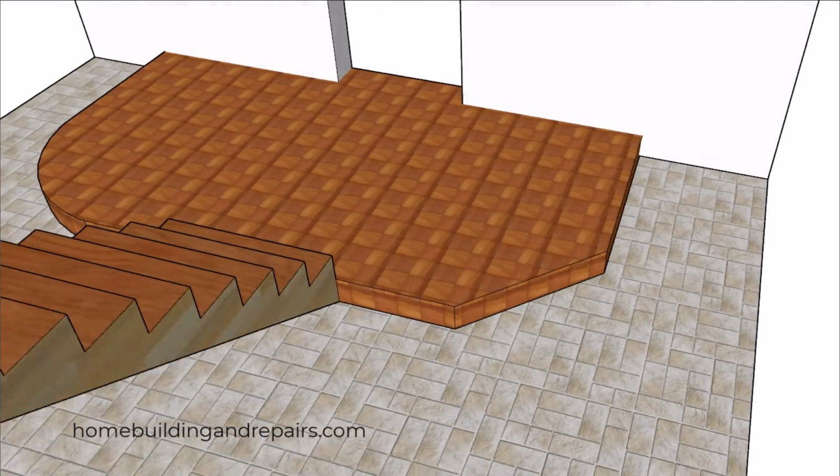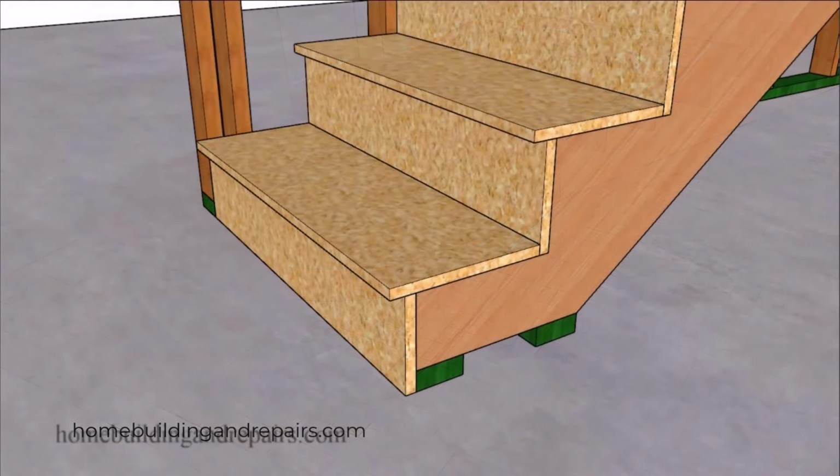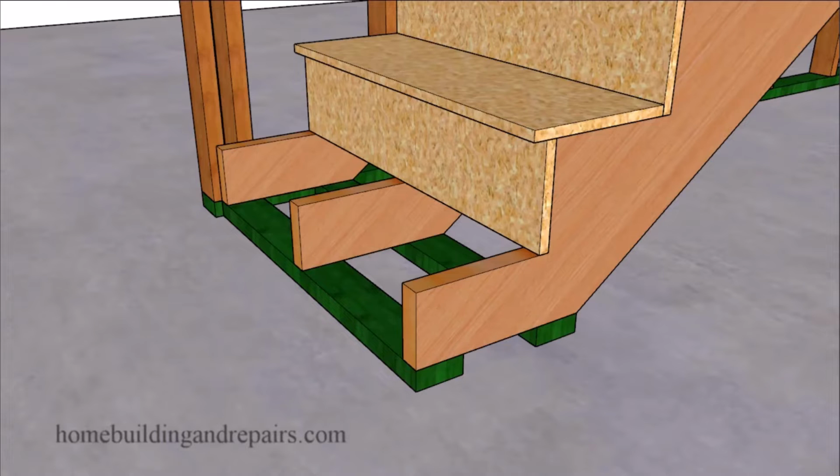Next up, let's go ahead and provide you with a few ideas that you might be able to use to add a landing at the bottom of a stairway. Now, the first thing you're going to need to do will be to remove the first riser in some cases, or the first tread. Now, you won't need to remove these all the time. However, in our example, we are going to remove them and measure the height of the stringer that sits on top of the treated lumber.